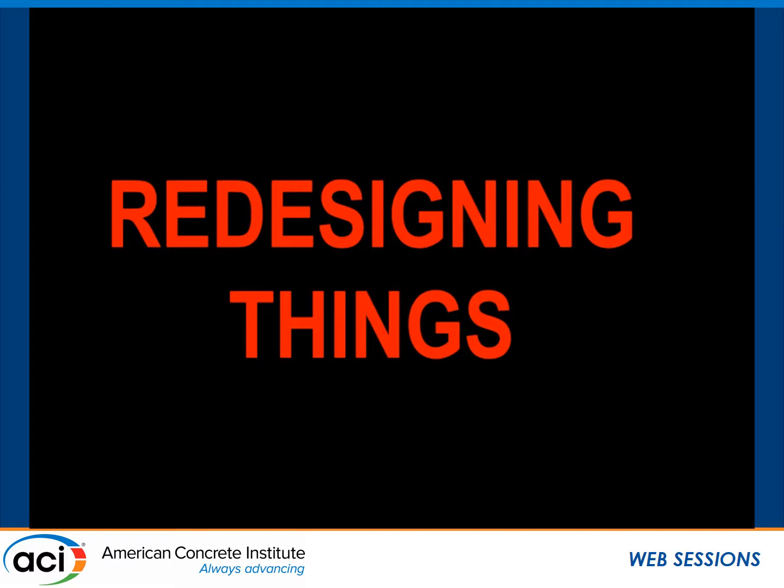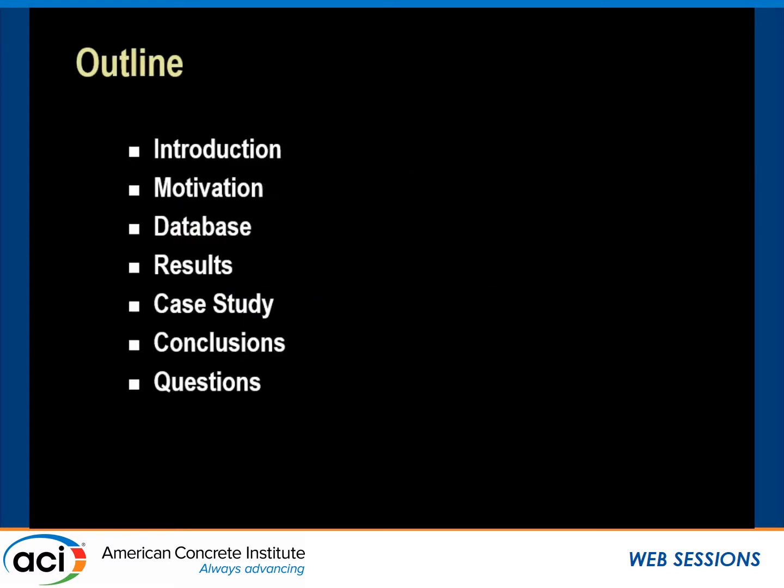It's useful for all parties involved because you can get a really good estimate of the proportioning of the building early in the design prior to completing the actual MCE analysis phase. So what do we not like? Redesigning things. So that's what made us start thinking about this study of looking at what are the actual amplifications from DE to MCE and SLE to MCE for both shear, but not only shear, also moment in core walls.